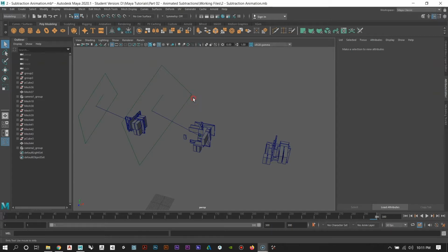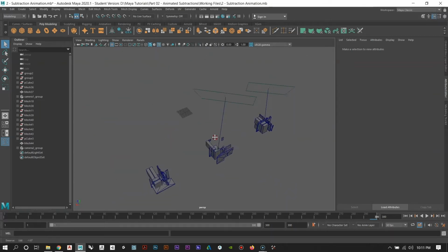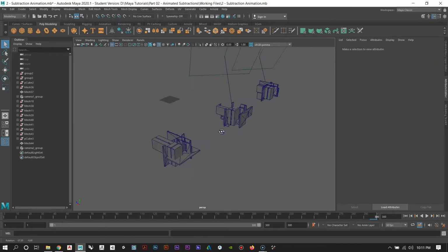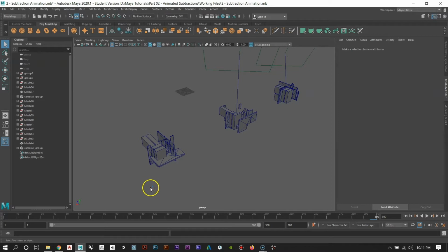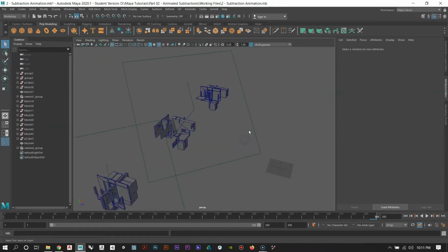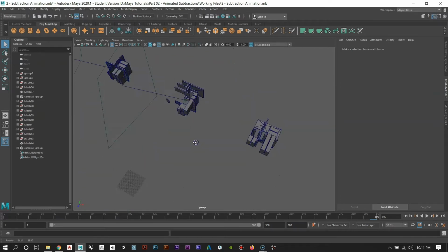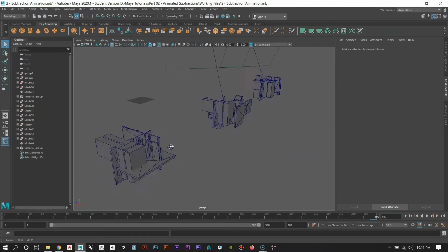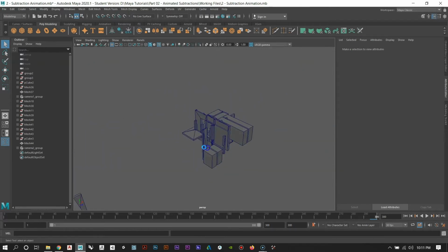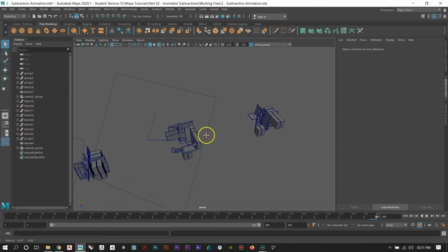Okay, so the next animation technique I'm going to show you guys is how to do an animated section cut. What we'll do is create literally a plane that can pass through our object and produce a section as it moves through. And then we're also going to produce what's called a double-sided material, so that when the section cut is taken, it actually looks like you get that, again, that kind of black poche effect. So it looks like a section cut.